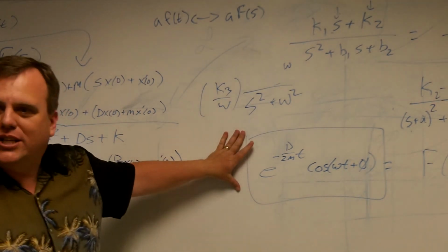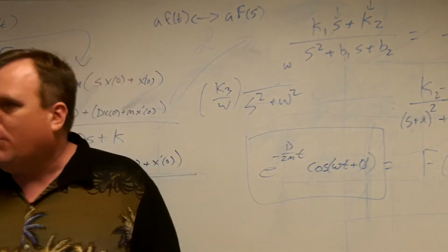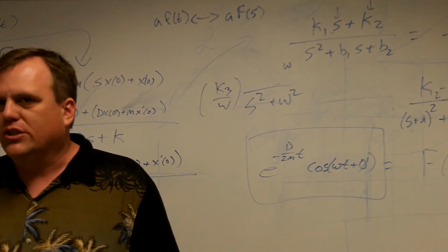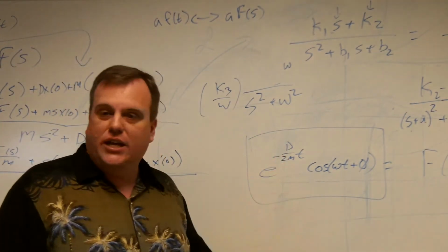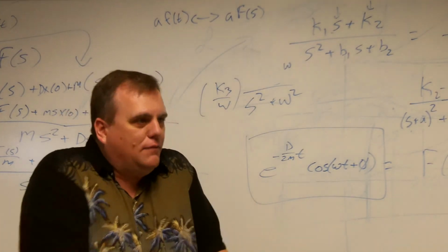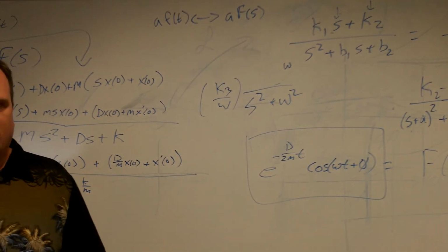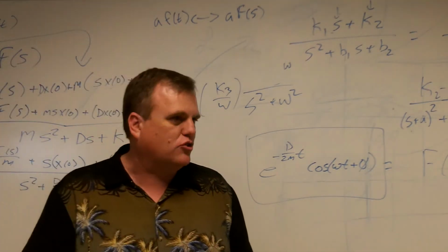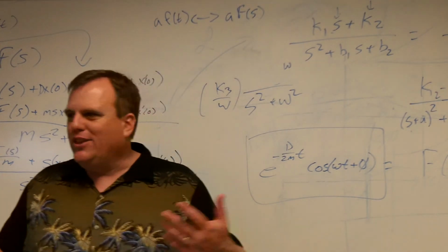But realistically, for a practical system, that is not going to be it. You would need active components in order to do this. For passive components, spring mass systems, this is guaranteed to be positive, which means it's guaranteed to damp. You have to have something that can supply energy into it, which means I need a motor or something else where I can be pumping energy from some external source. And that's the same for passive electronic circuits too. That's why they always damp.